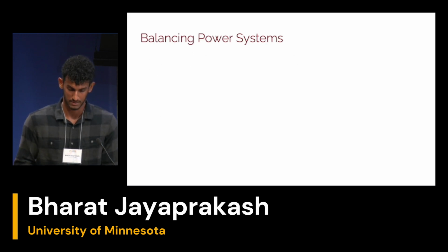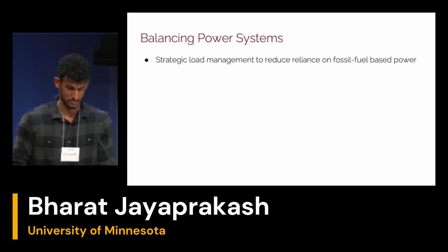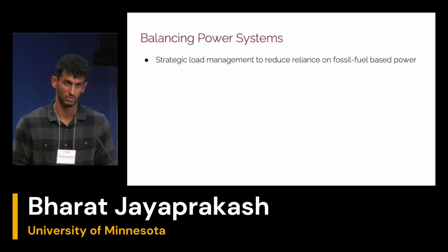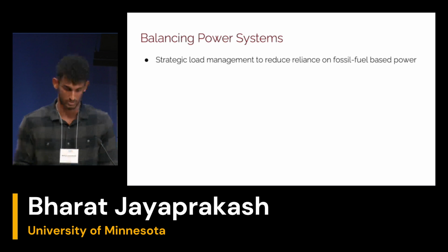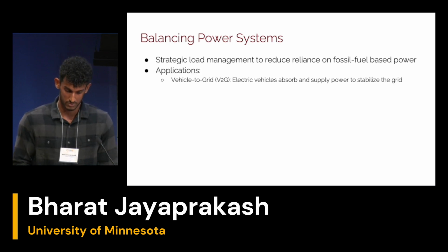The second subdomain that we discuss in the paper is balancing power systems, which mainly involves the management of load of power grids by strategic management of consumer side activities with the aim of reducing the reliance on dirty energy and increasing grid stability. And one of the most prominent applications in this subdomain is the vehicle-to-grid system, or the V2G infrastructure, which is a pretty well-established infrastructure and is also deployed at a very decent scale.